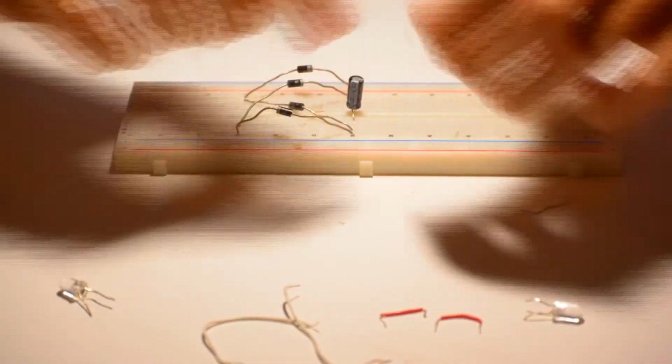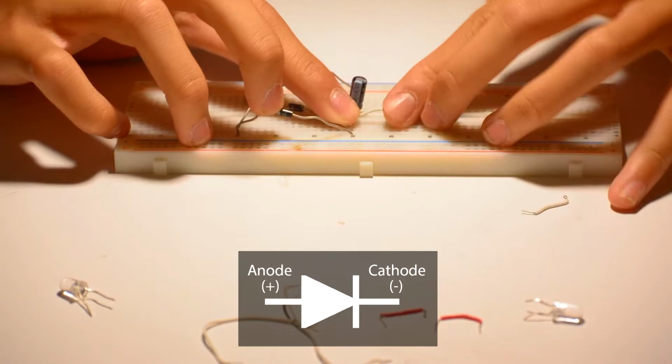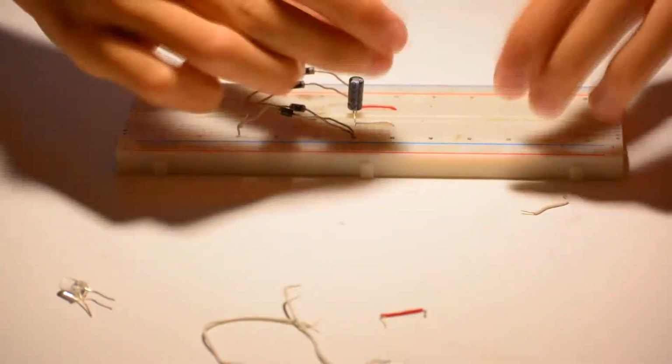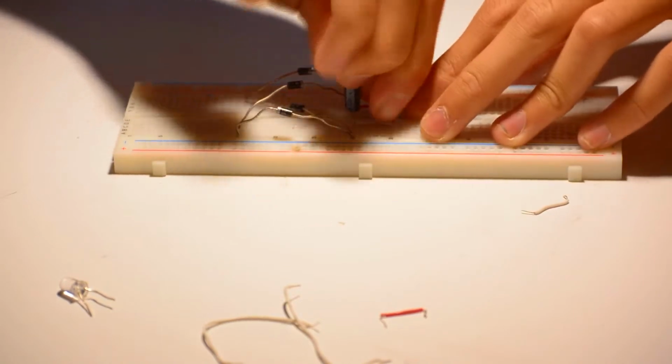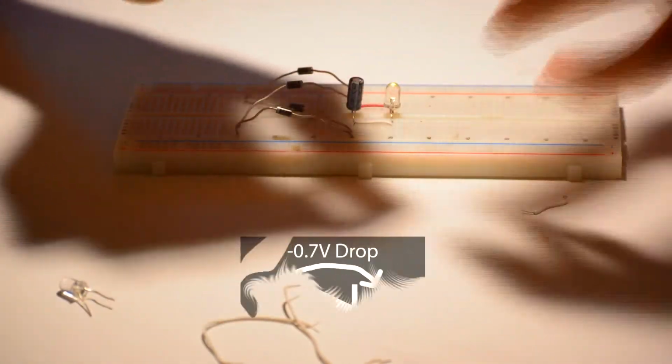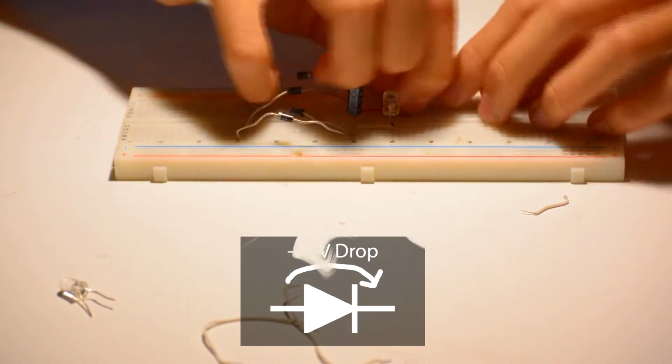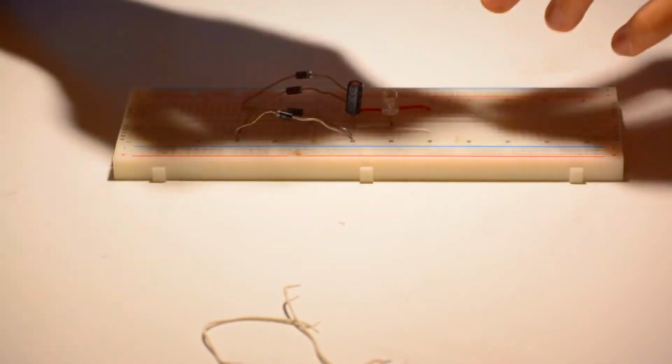After I check that the diode's anode and cathode are in the correct position, I attach the electrolytic capacitor to further stabilize the voltage. The only disadvantage of using a diode circuit like this is the annoying voltage drop of around 0.7 volts. Thankfully, I have used a specific diode with a very low forward voltage drop of only 0.4 volts, which is not that bad.